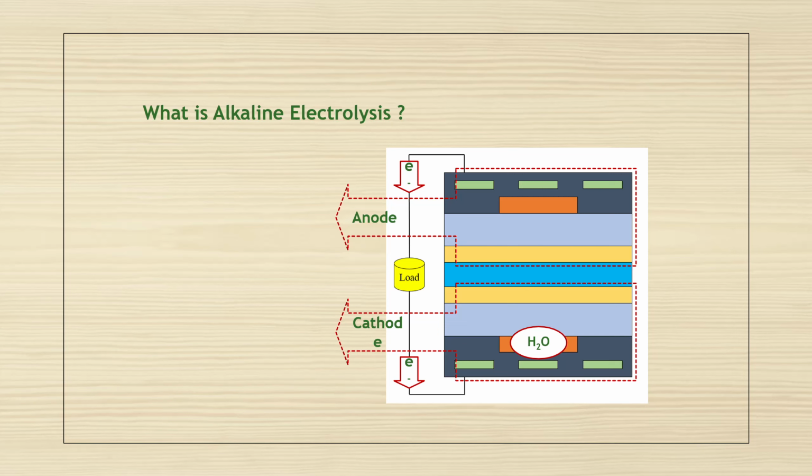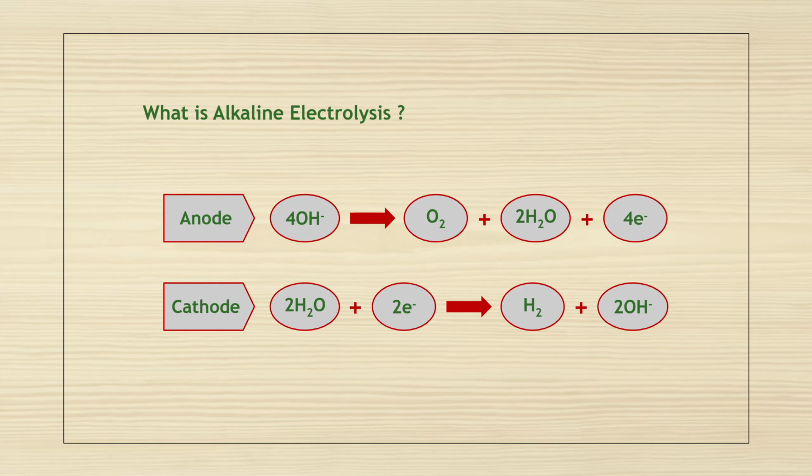Water flows in the channel on the cathode side. Also, since electrolyzers are power-consuming devices, electrons are supplied from the cathode collector side through an external electrical circuit. In alkaline electrolysis, 2 electrochemical reactions occur in the anode and cathode catalyst layers.